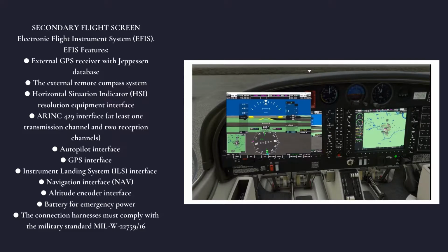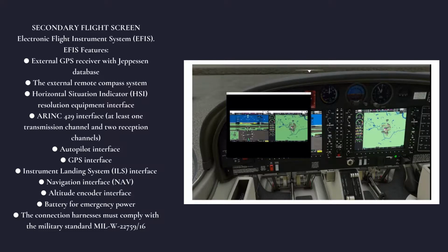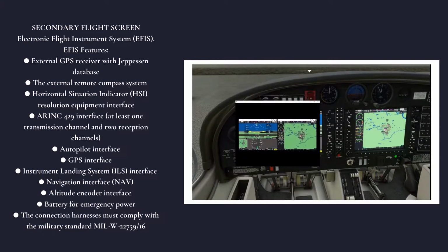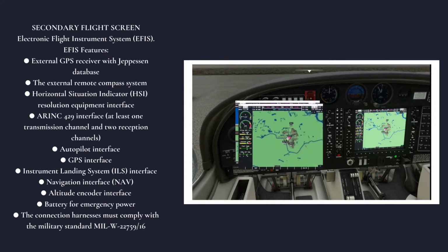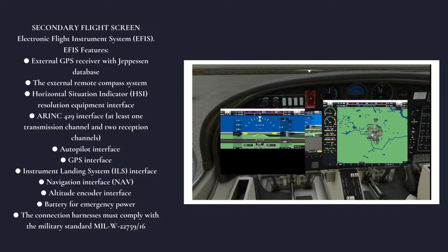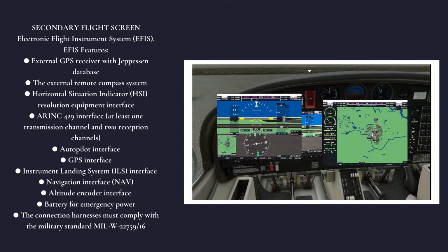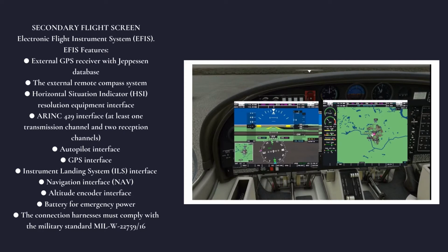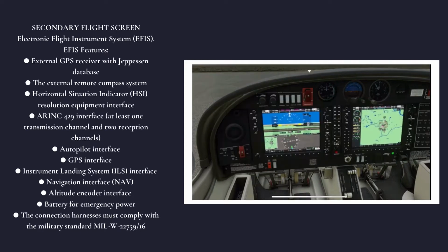The GPS data overlay includes text screens that display various information in text format. Text display includes track over ground (TRK), bearing CRS, ground speed (SPD), distance to next waypoint (DTW), and up to two direction indicator selection.